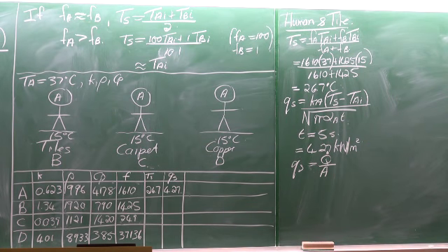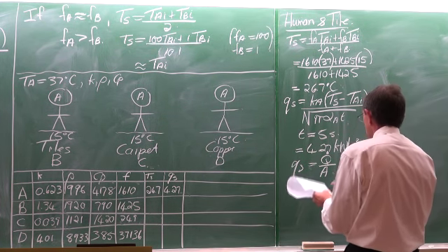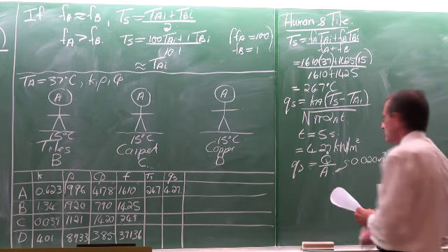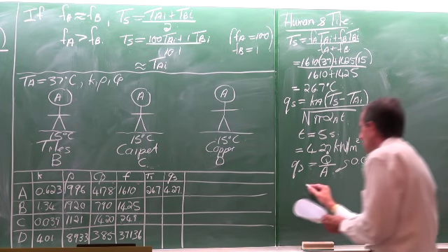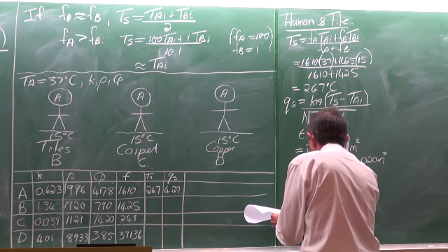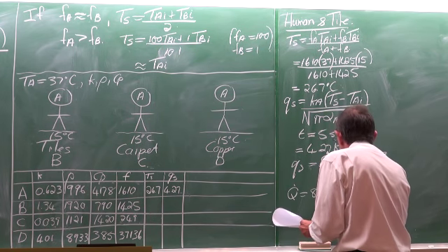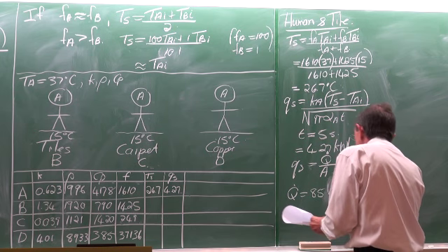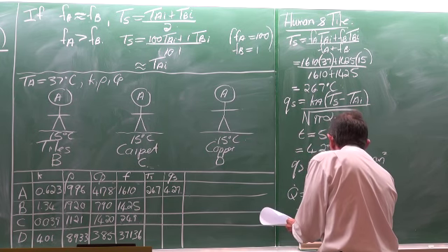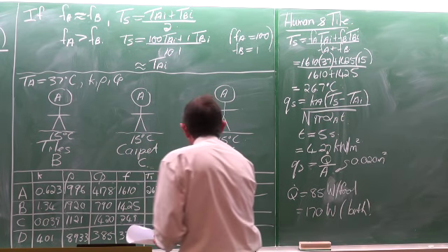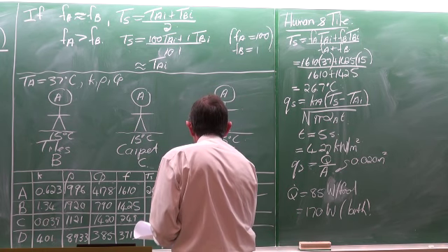Yes, every one of you, your surface area for your feet are different than that of somebody else. But let's suppose it is about 0.020 square meters, which would be sort of an average. Then we can calculate the heat transfer rate as 85 watts per foot. So for both your feet, it would be about 170 watts.